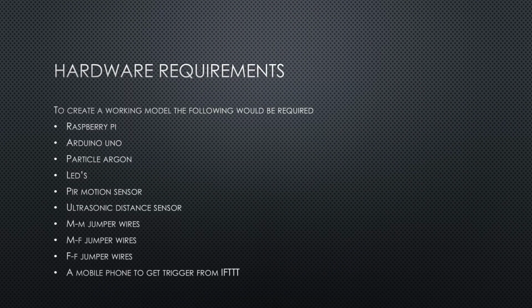We'll be requiring certain hardware to make the working model of the Sanitech. So what we are going to need is a Raspberry Pi, an Arduino Uno board, Particle Argon, LEDs, PIR motion sensor, ultrasonic distance sensor, male to male jumper wires, male to female jumper wires, female to female jumper wires, and a mobile phone to get a trigger from IFTTT.